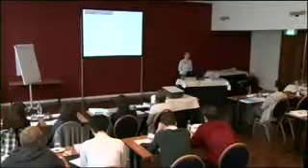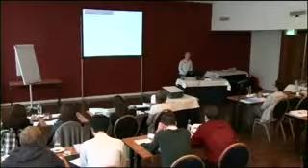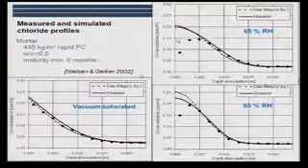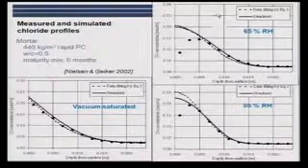And then we knew the sorption isotherm, so we could translate the relative humidity to degree of saturation. We exposed the samples to chloride. Here they were exposed to a solution. Here we exposed them to a brine, a very concentrated solution, for a few hours, and then removed the water again to keep them at the right relative humidity.